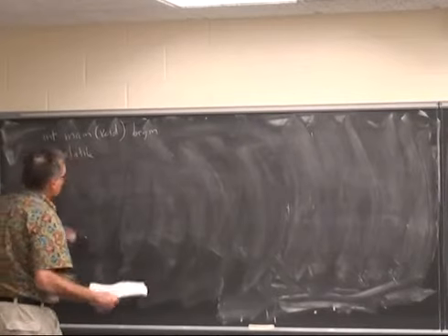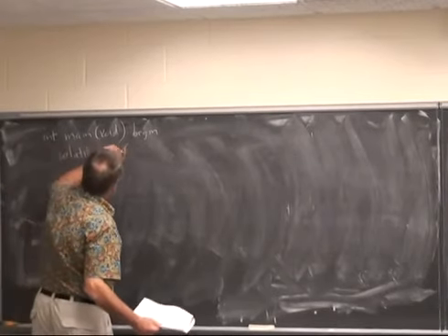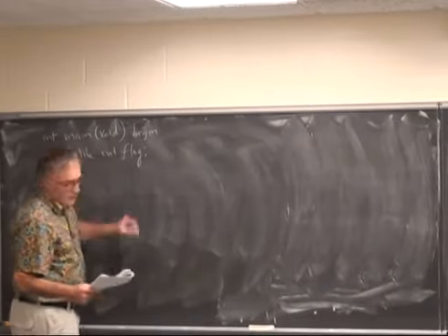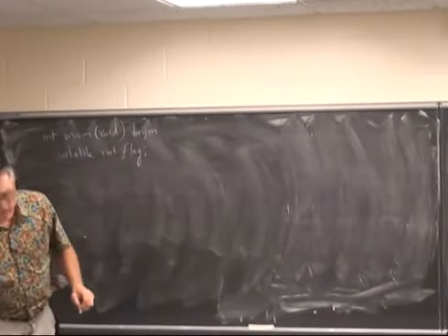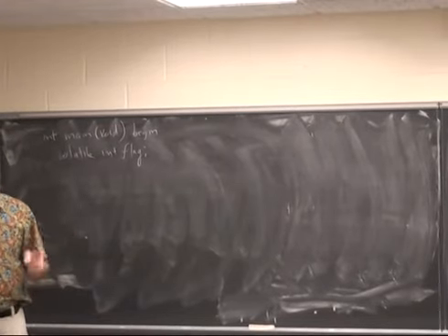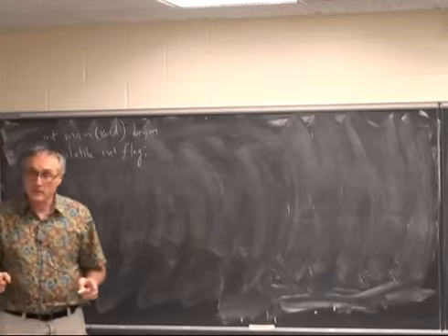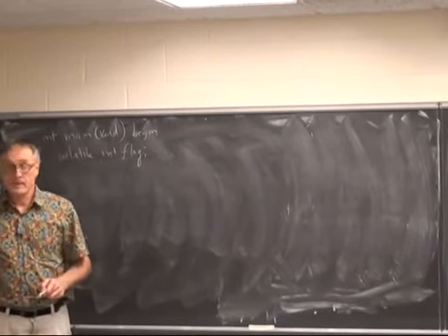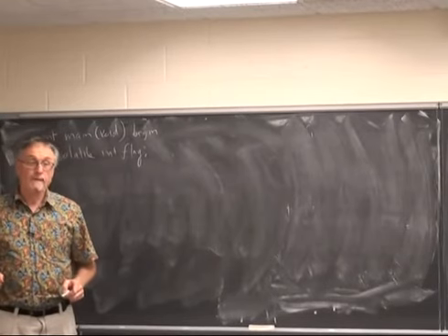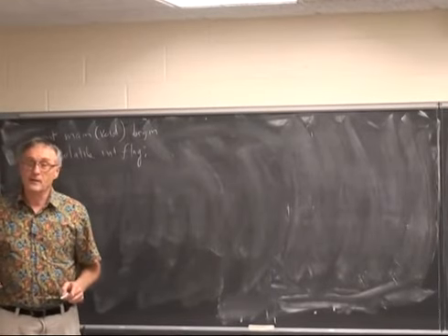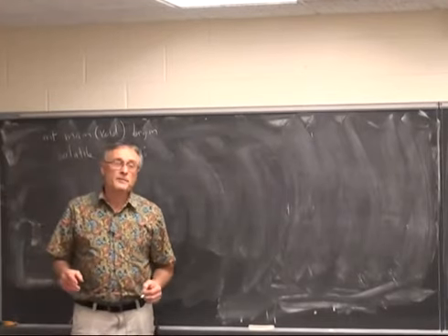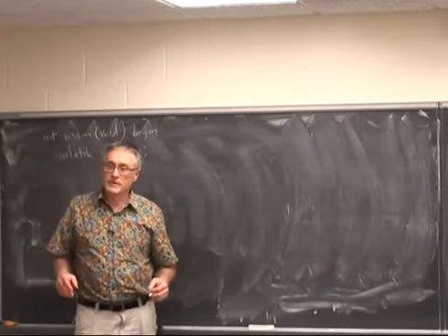And we're going to define a volatile int, which is flag. And I should emphasize that any variable which is shared between an interrupt and main has to be declared volatile. The reason is the compiler is very good at optimizing away variables that never change.